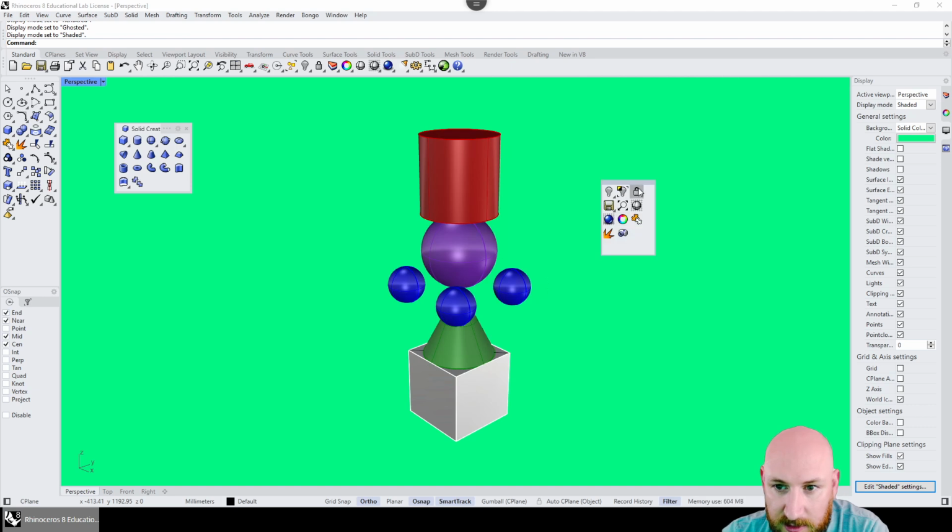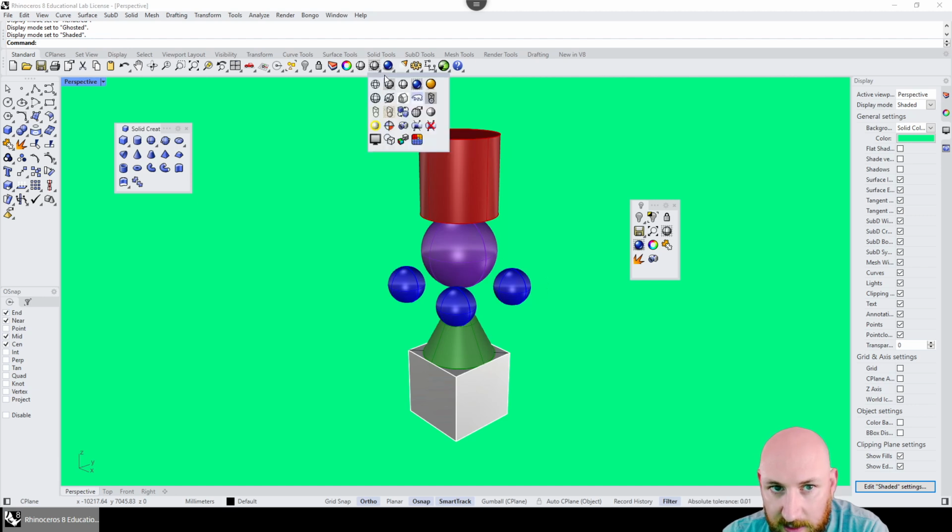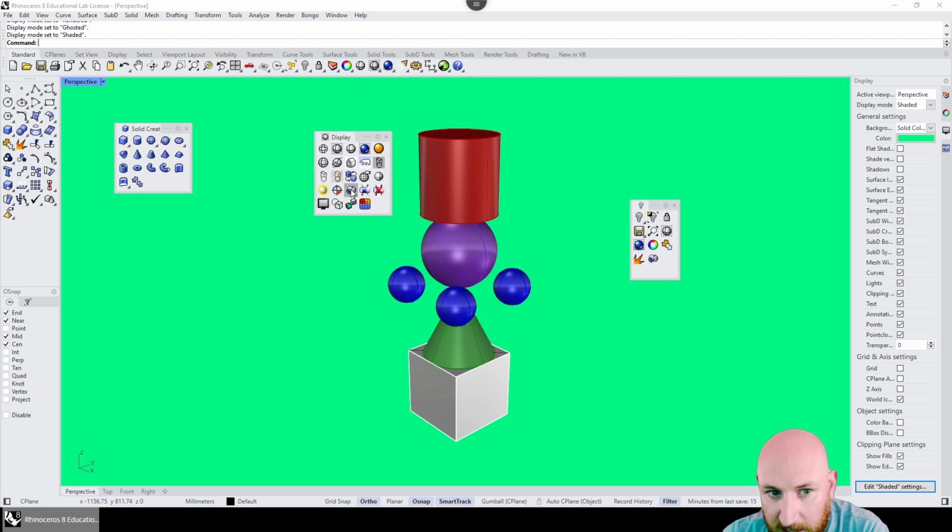And you can double click that, change it to green. And now if I use this menu here, if you missed yesterday's lecture, one thing I did as well is I left clicked on the shaded viewport, and I left click and hold the top thing to drag it out. And holding down Control will copy this icon from this menu to this menu. But holding down Shift will move it, which means it will delete it from the original menu, which you really don't want to do. So you can hold down Control and move that from there to there. Now I've got a double one, so I'm going to hold Shift and move it off, which will ask me to delete it.